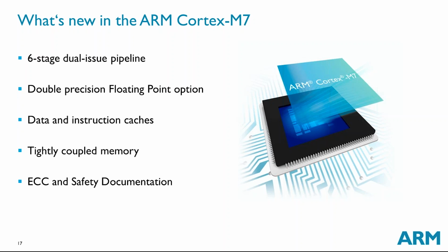in the coming months. The third point is the Cortex-M7 design includes caches for data and instructions, and also tightly coupled memory that sits closer to the core to avoid bus accesses and wait states for frequently executed code. Together, these features enable the ARM Cortex-M7 core to reach up to 5 CoreMark per megahertz, which is a lot more than comparable MCU solutions.